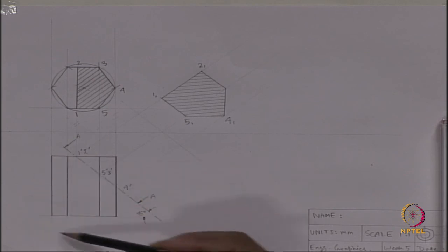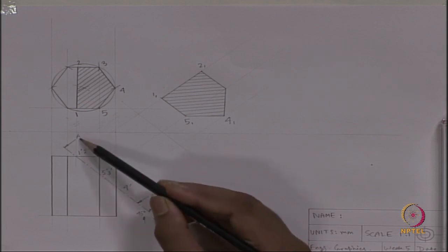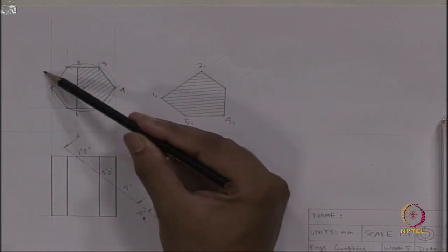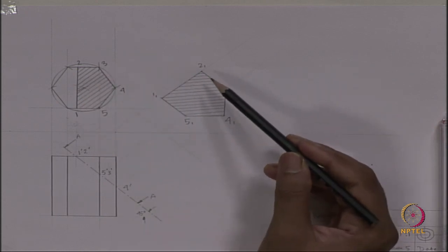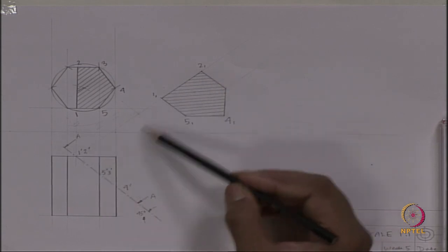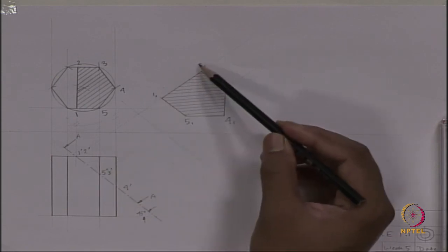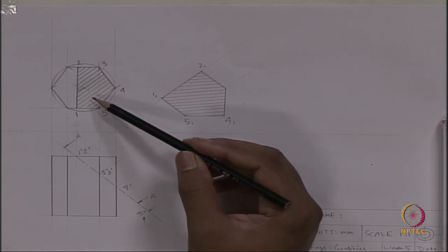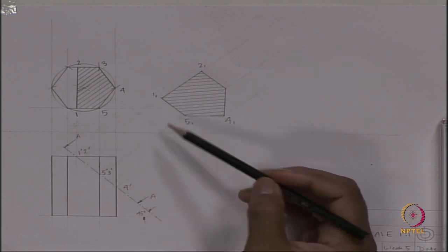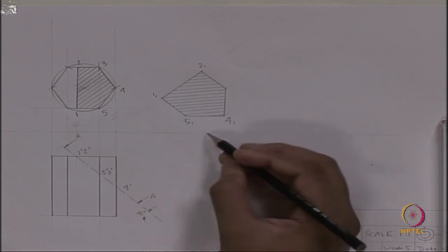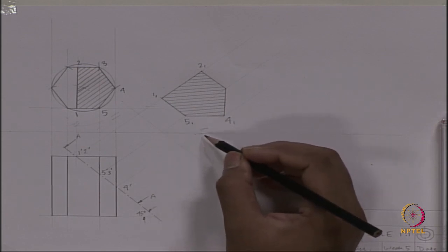This is the front view along with the cutting plane. After cutting, we have got this sectional top view. This part is the section, and this is the auxiliary view of the true shape of section, where we have taken the projection lines from the front view, which is the adjacent view, and to get the exact location of those points we have taken help from the related view, which is the sectional top view. So, these distances are equal from the reference line, but you should not show these marks when you are drawing.